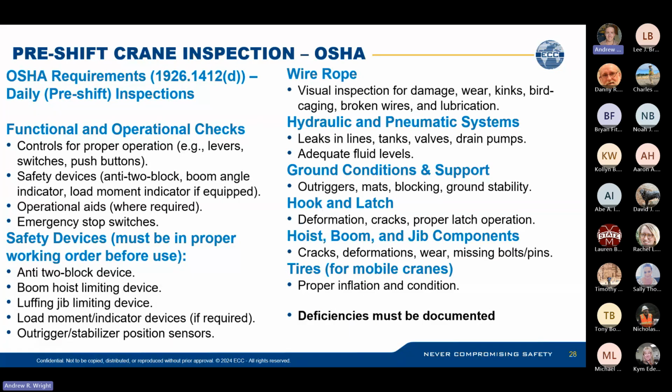All right. Pre-shift crane inspections per OSHA. This is in the 1926.1412 subsection D. These are your daily pre-shift inspections. They include a functional and operational check.